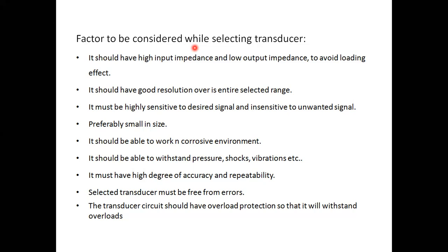And if the error is dynamic, then I can't assess the magnitude of error from measurement to measurement. Why? Because the error may vary rapidly from one measurement to another. And an instrument must have optimal sensitivity. Why? Because if the system is highly sensitive, then I have to compromise on stability. And if the system is less sensitive, it may pose errors for me.